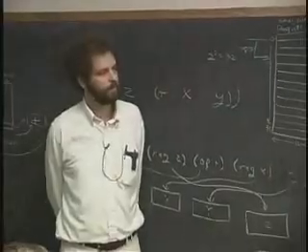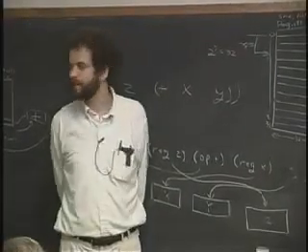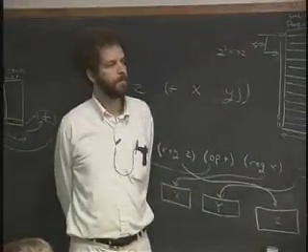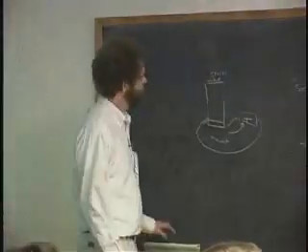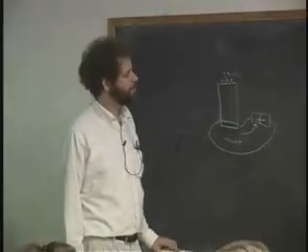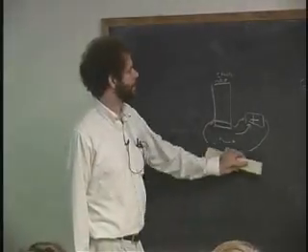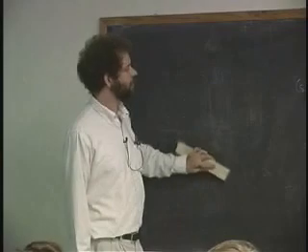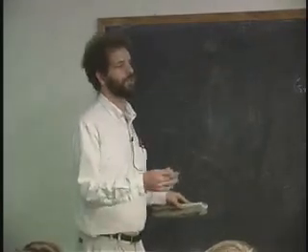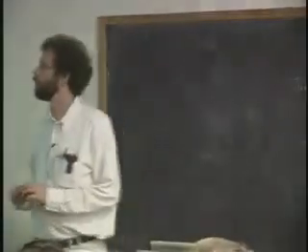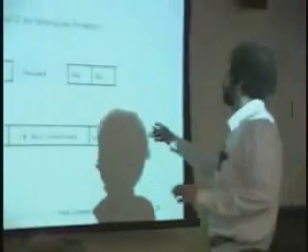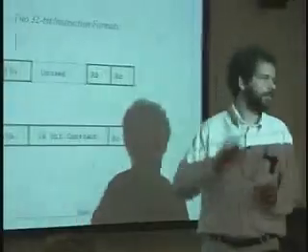I'm wondering, is the assignment or the storing, is that implicit in the operation code? Yes. Or in the instruction set? Because when we did it here with our RTL, we had the assign and we told it explicitly to assign. That's absolutely right. There will be special opcodes, load and store, which will do what we want to do. Otherwise, what the opcodes will do is always store into what register C tells us what place we want to store. So you'll actually see that as we go through, okay?